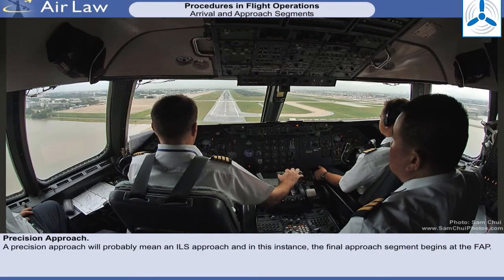Until standalone GNSS precision approaches are fully developed, a precision approach will probably mean an ILS approach, and in this instance, the final approach segment begins at the FAP. You should recall that this is the point in space on the center line of the localizer specified for the final approach track, where the intermediate approach altitude or height intersects the nominal glide path.